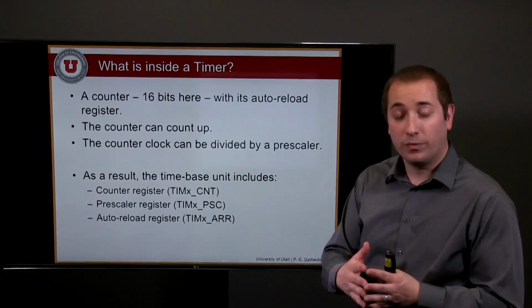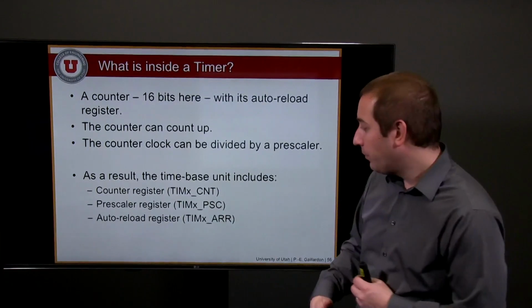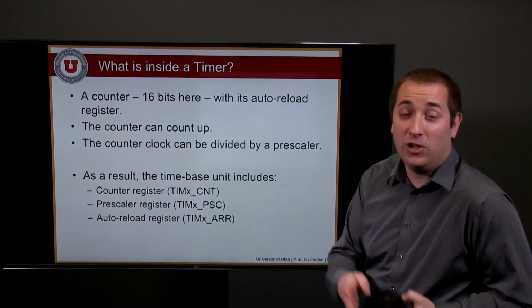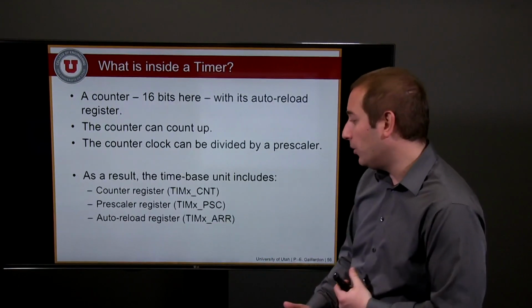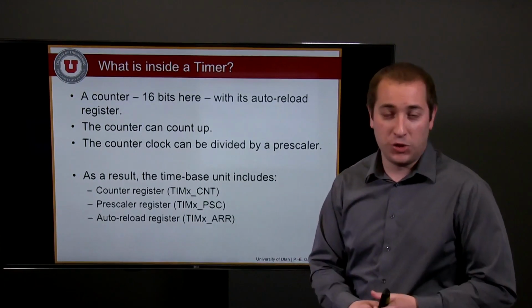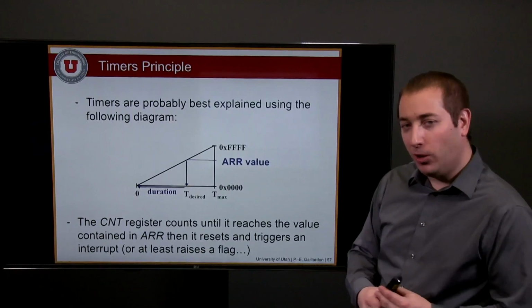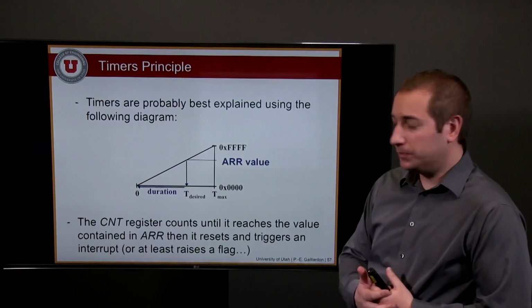It will include the length of the counter register. It will consider the prescaler register, so what is the clock frequency you use to increment this counter, and the auto-reload register, from which value am I starting. So the timer's principle will be best explained with this diagram.